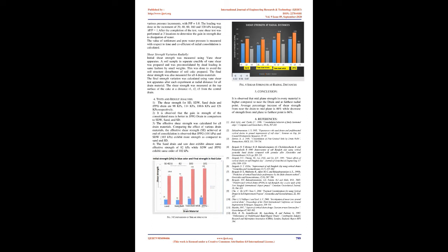In the present investigation, sawdust wrapped with Whatman filter paper, SD, sawdust wrapped with geosynthetics, SDW, sand drain, and jute wrapped with polyamide polyester, JPPG, are used for investigation. The properties of the drain material are shown in Table 2, Table 3, Table 4 and Table 5. The sawdust is treated chemically and then used as a drain by encasing it with Whatman filter paper.